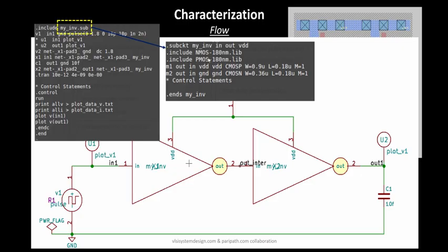So the subcircuit actually contains the NMOS and the PMOS models. It has got the connectivity of an inverter. So this inverter is being loaded twice. So what you see in this particular diagram on the right side, this inverter is being called from this subcircuit, this inverter is being called from this subcircuit, and when you attach them both together in the form of a spice netlist, you get this description of a buffer. Along with the description of the buffer, you have these capacitances and resistances, which will give you a description of an extracted spice netlist of a buffer.